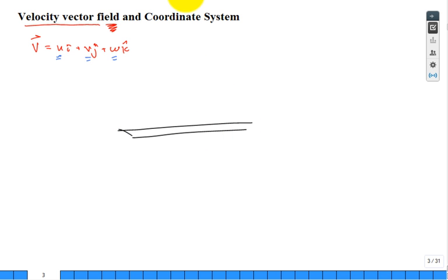So we're going to have this knife-edged flat plate. We have the fluid coming at it. We're interested in calculating at a particular point. There's the point right there. I would like you to be able to tell me what U is. What is that? That's the velocity at that point in the x direction, as well as what, and I'm not showing it to be even as large, V is. Now, the focus is 99.9% of the time on U. U at the location X and Y, not really V.